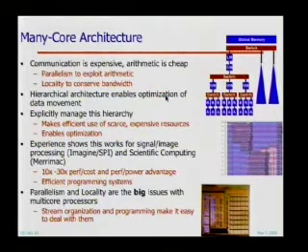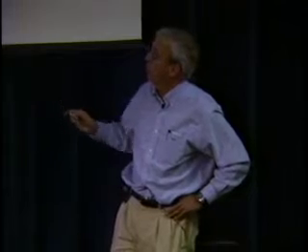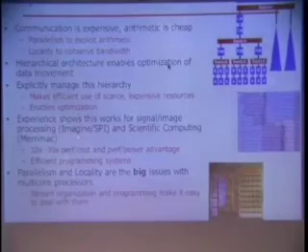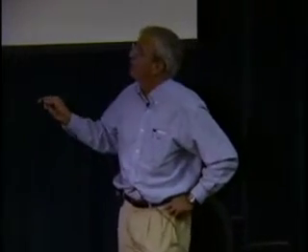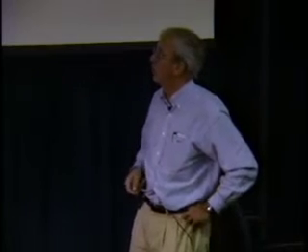And when I fire a kernel off, all of the data it needs, all of the instructions it needs are there, and I can get extremely high utilization by statically scheduling that kernel. We've tried this out both for signal and image processing on Imagine and for scientific computing on Merrimac, and have shown extremely good performance advantages and performance per unit cost and power advantages over other ways of doing it. And in that period, developed a number of very efficient programming systems.